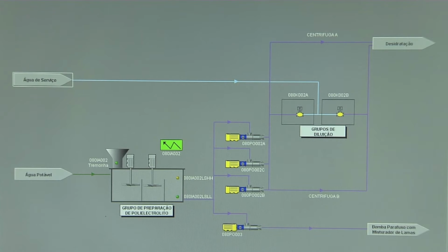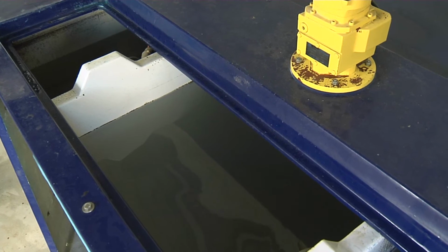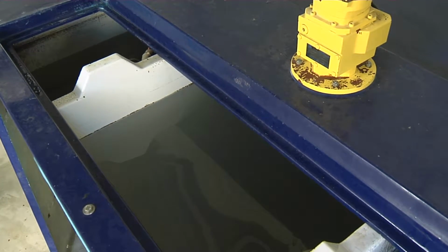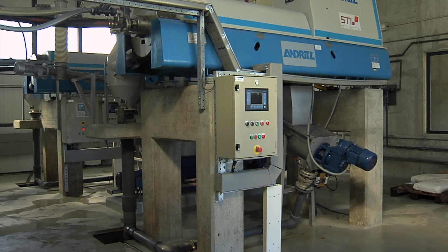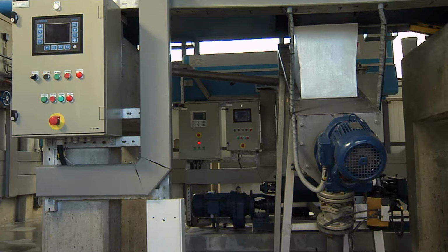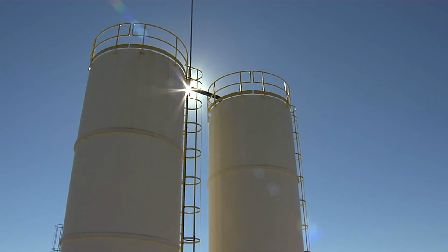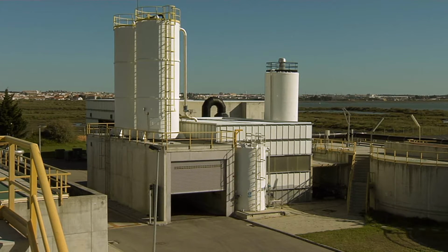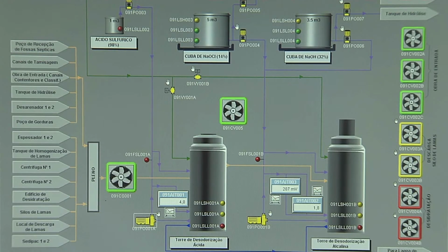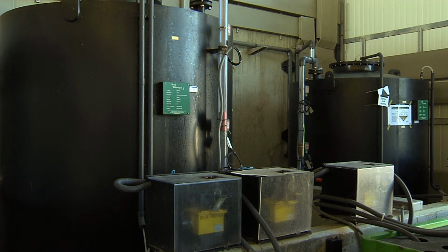Solid phase. As a result of the primary and biological treatment, mixed sludges are formed which, after removal, will be subjected to thickening and dehydration. Water extraction decreases the amount of sludge to be stored and transported for agricultural purposes.